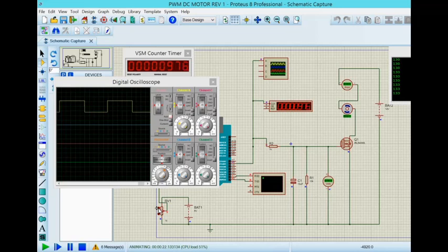So there's an intention of the motor starting to spin, because I can see a number here of about 3 RPMs or so. So at 133, you start to have some minimal action. Going up a little bit more, 135. Yeah, at 135 you start to see about 100 milliamps or so going through.